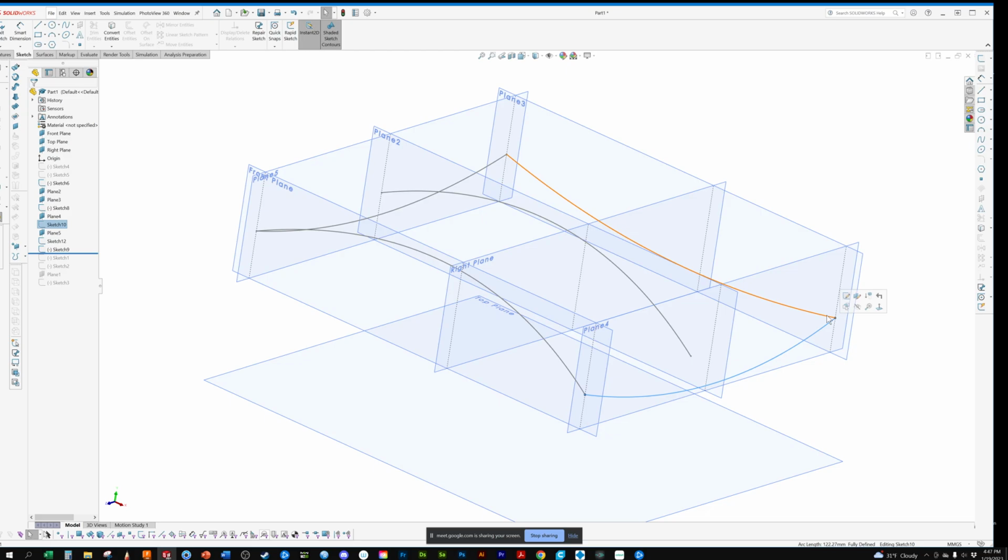What we need to do is come in and add relations. So we've talked about, we want this point, and we've talked about before, concentric and tangent and all that. We're going to have a few new relationships that we're going to talk to. And the main one, we've talked about midpoint, which is snapping that edge to the midpoint of a segment. We've talked about coincident, meaning that it just touches that line.